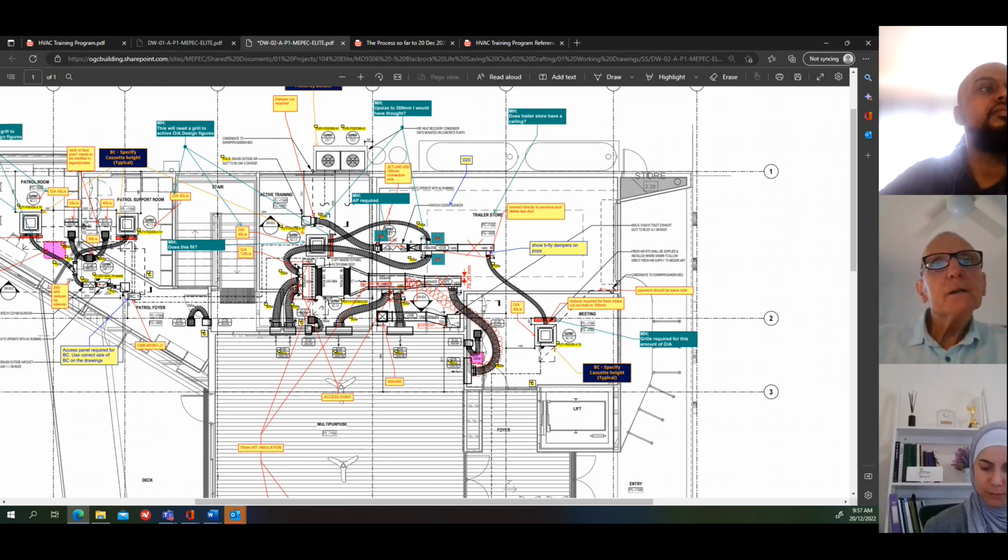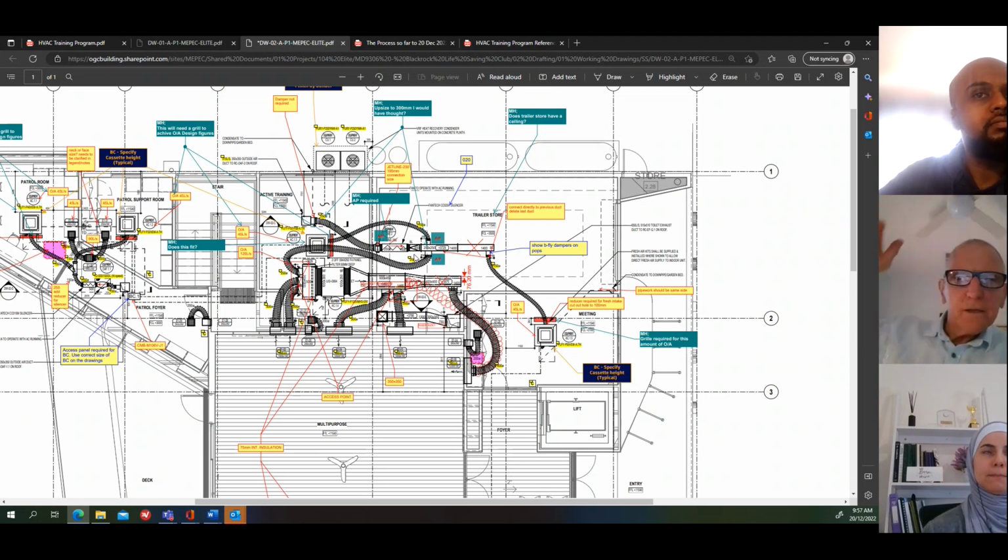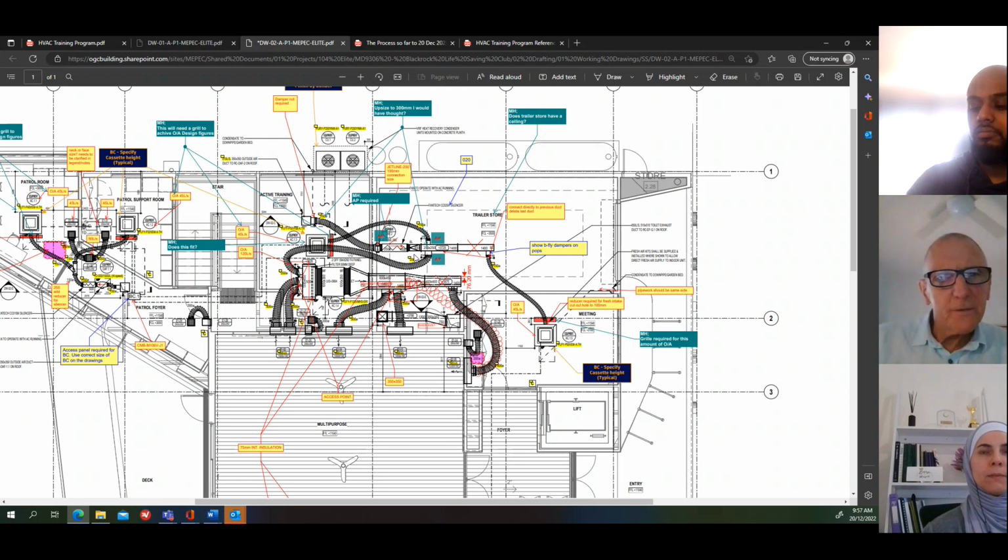Which means, and that's a straight transition in the plan, it's actually sloping on top. So it's coming down on the top. Bottom is flat. Top is sloping. Okay. This attenuator is 1,000 millimeters long. It's 250 diameter. That would be a proprietary attenuator from the fan company.